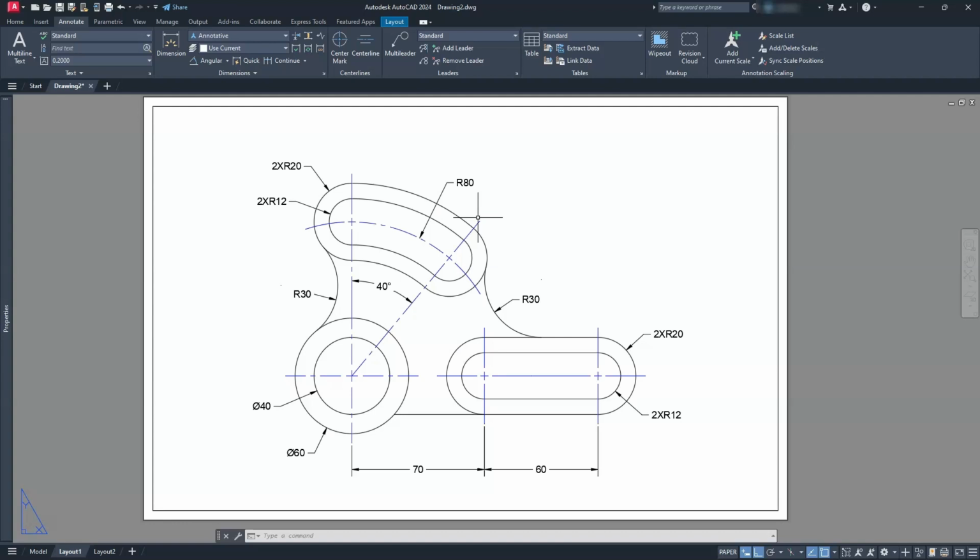And you will also see that if I put dimensions out here, so if I just use a regular dimension, they should be exactly the same size. So these dimensions are created on the outside of paper space, but you can see that they look exactly the same. That's why I like using my dimensions on the outside, but if you're going to do it on the inside, just make sure that you match the viewport with whatever your scale is on the annotation option, alright?